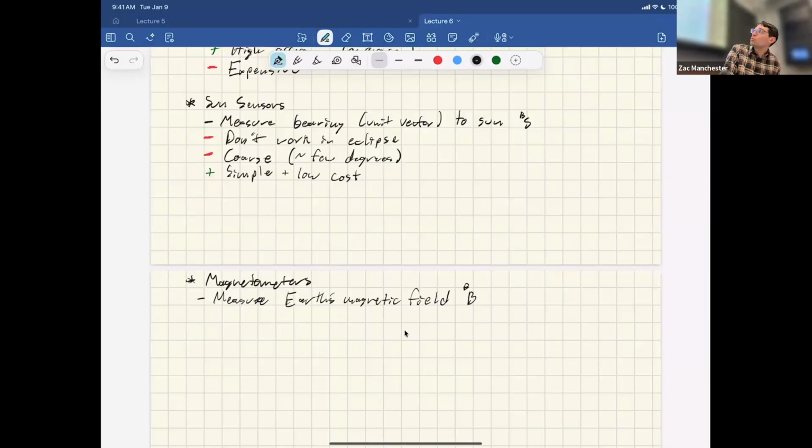They're actually super interesting. These are very common for attitude determination in low Earth orbit. They're also increasingly being studied for navigation, like for orbit determination and generally GPS-denied navigation. The reason is that there's a revolution happening around quantum sensors, where people are able to build insanely sensitive magnetometers. And if you have a good map of the Earth's magnetic field, you can actually figure out where you are using a magnetometer, which is kind of cool. So it's an emerging thing that's pretty interesting.